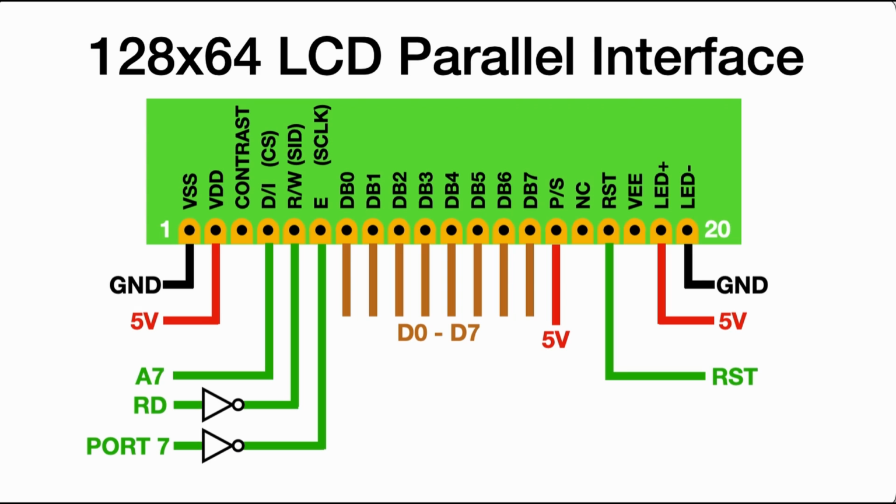I have noticed the backlight is very bright, so probably a resistor here to reduce the voltage will be better. I don't use the backlight. And then we've got 3 leftover pins. They're not connected to anything. VEE is just an output power. NC is you don't connect it.